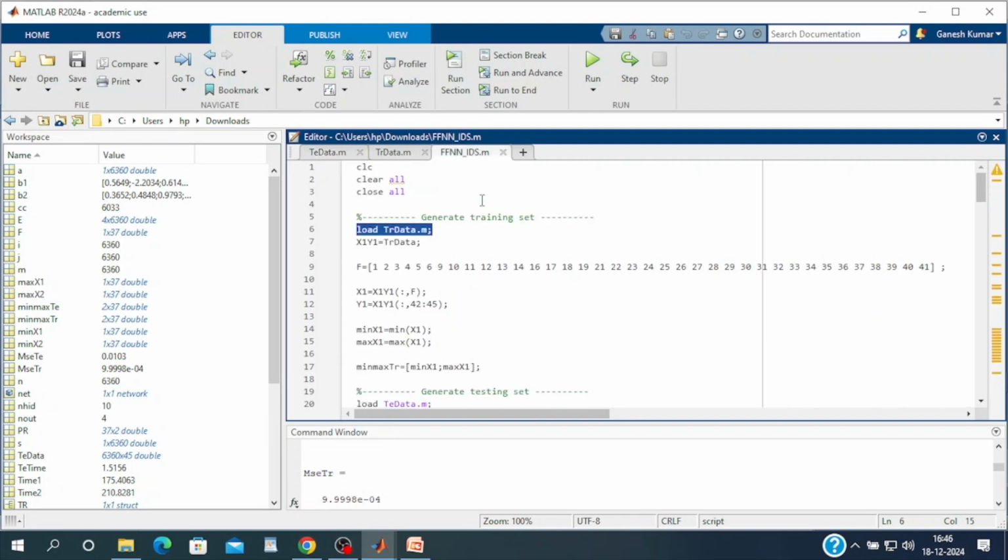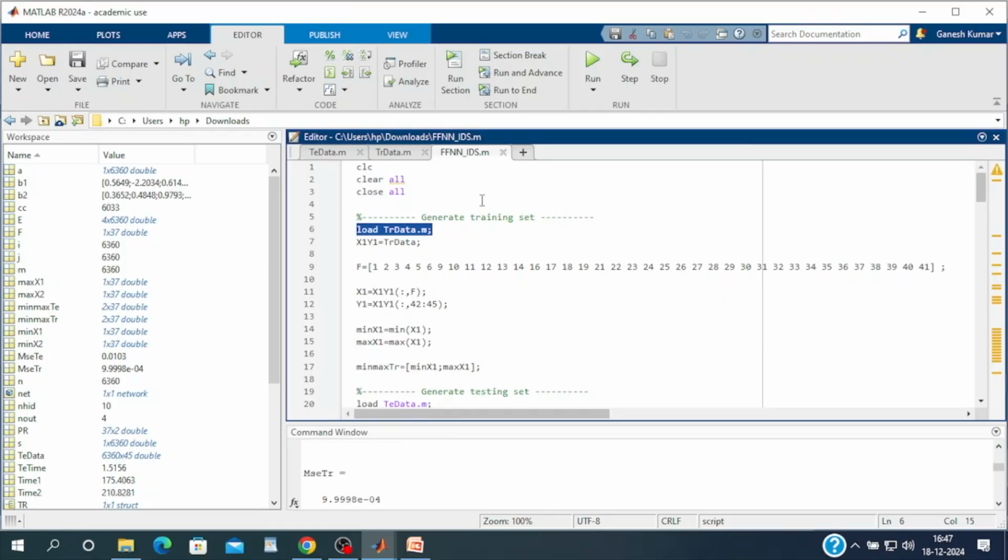I informed you in the previous presentation that your entire MATLAB code development can be discussed in 3 phases. The first phase is data loading, data separation, and data preparation according to the ANN model development. The mid portion is network structure creation, initialization, training and testing. The last portion is visualization of the results, which needs some logic in order to map the network output to the actual output.